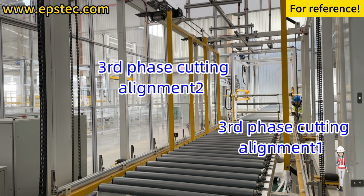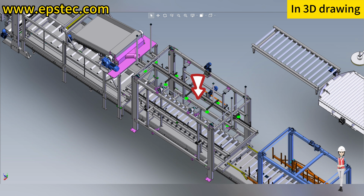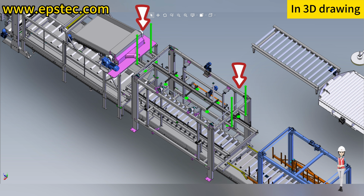Perform the following action. The third phase aligned cylinder 1 extends. The aligned cylinder 2 extends. The third phase cutting position cylinder retracts. Top press plate cylinder downwards, and the waste blocking cylinder extends.